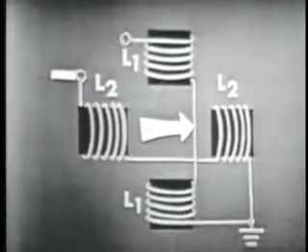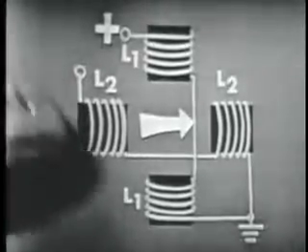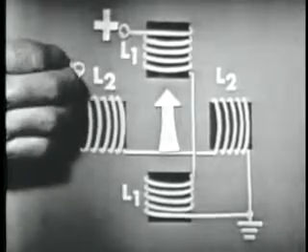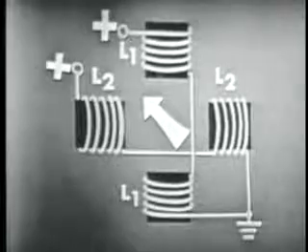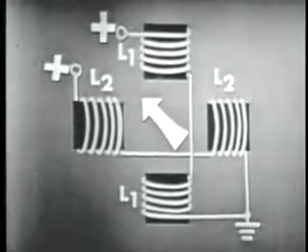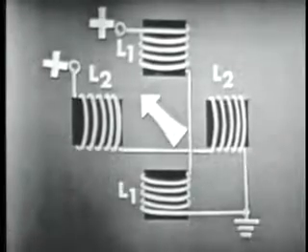And we can also energize both coils at the same time and produce four more directions. Okay, positive. Now, by supplying both L1 and L2 with this polarity, L1 produces an up direction, L2 produces a left direction, so the two equal fields combine and move up and left at this angle.